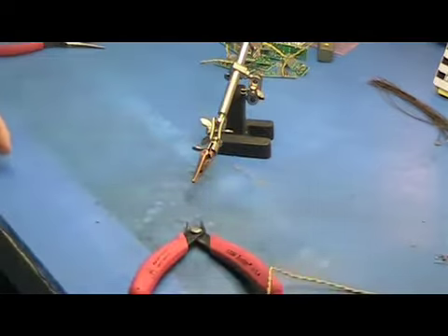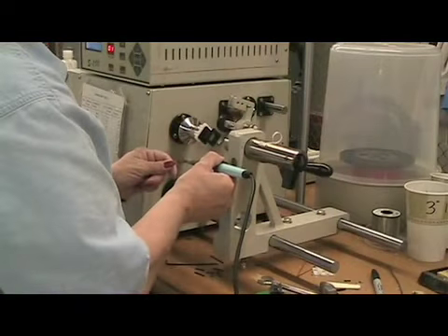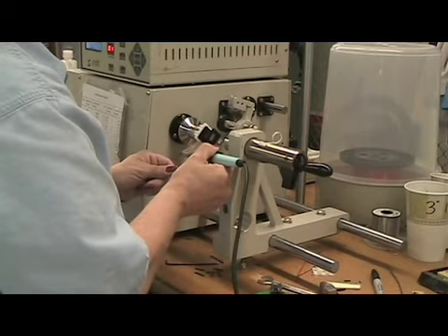Now, with respect to why open loop or closed loop, I really think the open loop is a cost consideration. Open loop has some drawbacks of linearity, temperature dependency of the output, and zero offset stability, but all that being said, it still is a very accurate method for measuring current at a very low cost. Whereas with the feedback style, you actually have to put windings on the sensor to create an opposing current to the current that you're trying to measure.